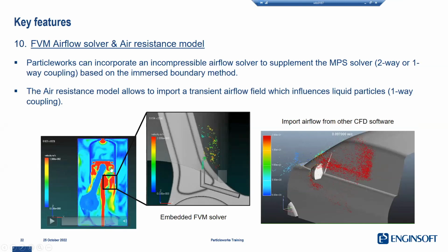Ultimately here we want to map the HTC on the piston and see what are the cooled regions. And actually we would like to transfer the HTC map to a solver for the thermal aspects of the piston and understand what the max temperatures are. This is just the beginning of the simulation. What we see here is the velocity field. So red means that we have velocity higher than 100 meters per second, in this scale. So it's just a velocity field of air. Red doesn't mean good or bad in this case.